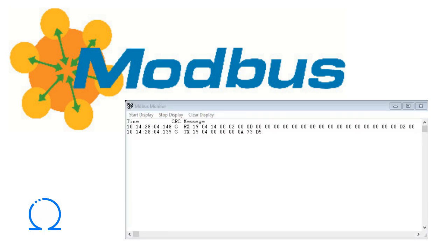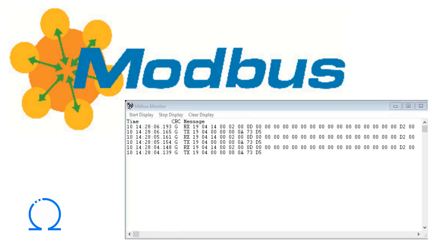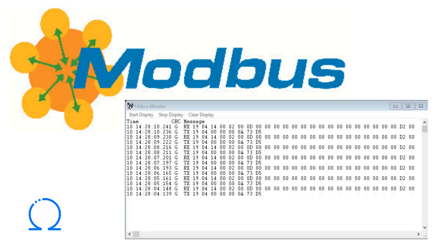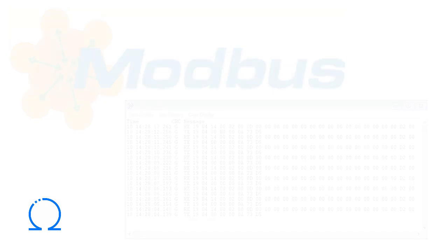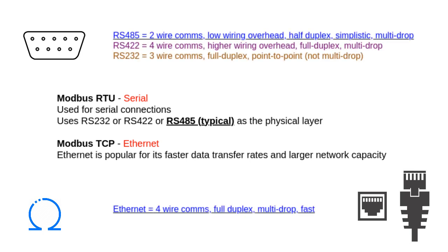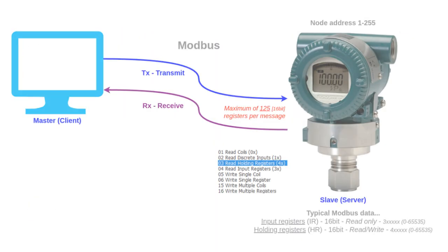Modbus is a commonly used data communication protocol that is based on a request-response model. It can operate across multiple physical communication types including serial and Ethernet. Serial communications commonly include RS-485, RS-422, and RS-232. Because the Modbus protocol is used to exchange data over a variety of network types, it continues to be widely used in industry for both new and legacy projects.